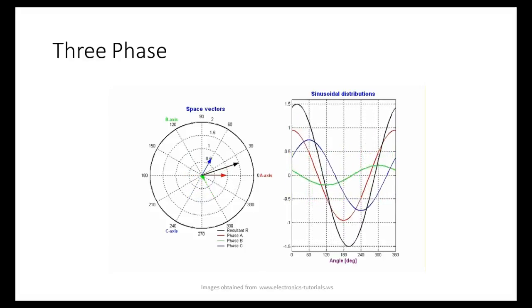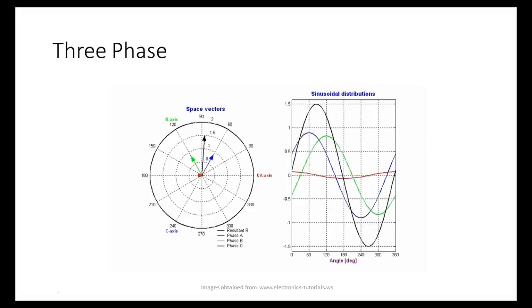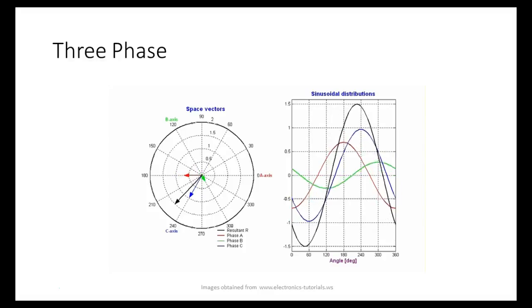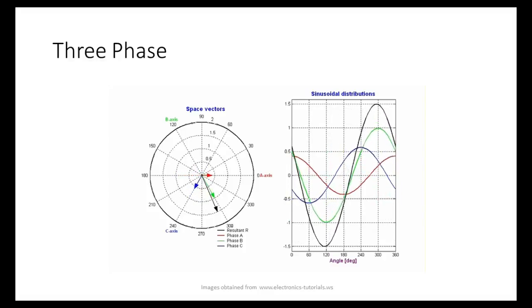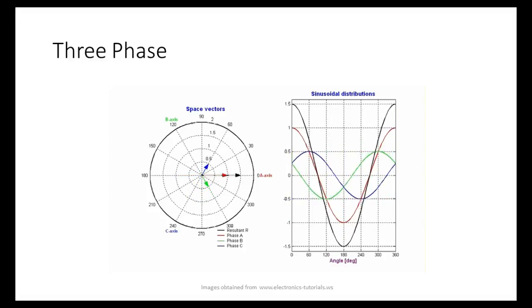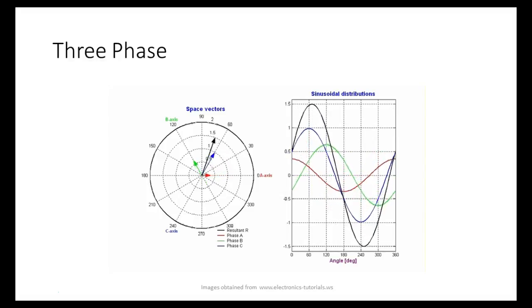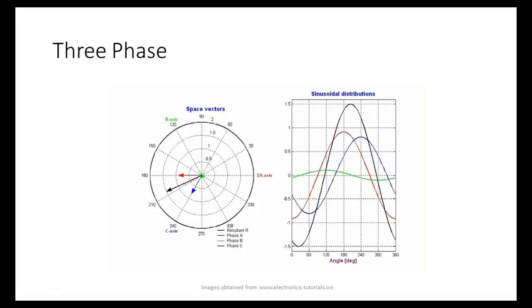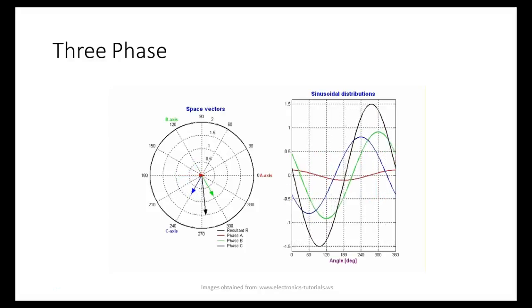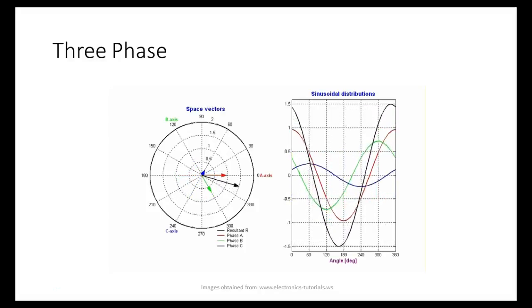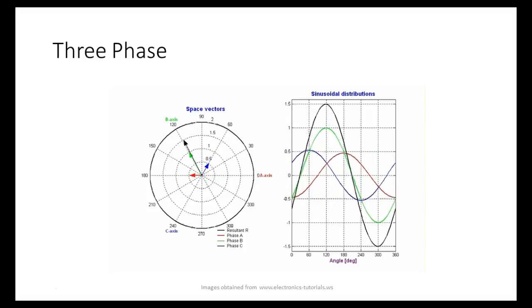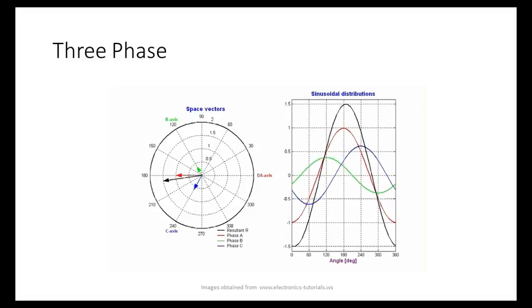What you're trying to do is balance the loads on your three phases. Well, a three-phase motor is a balanced load anyway. So I'm trying to run single-phase loads, and you want to keep your loads balanced on the three phases. Do you understand what we're saying?